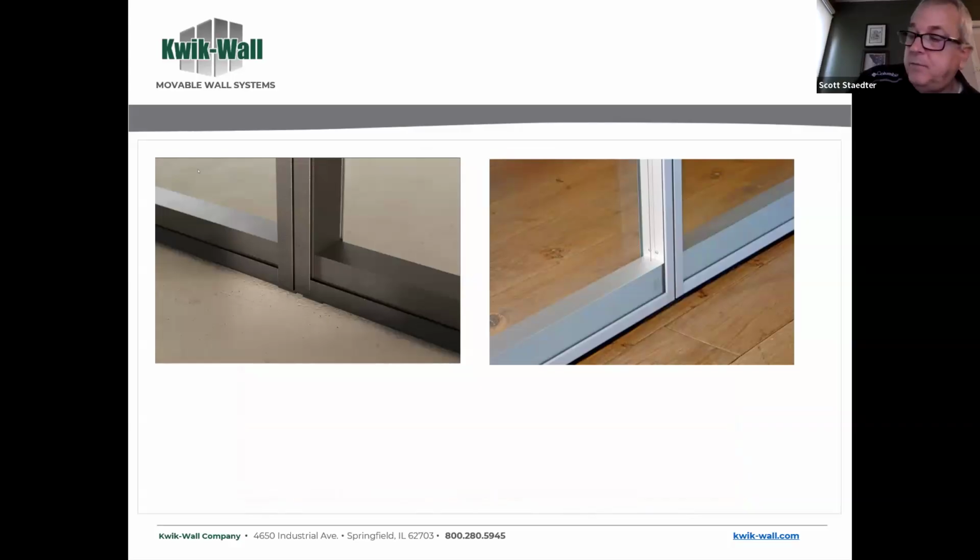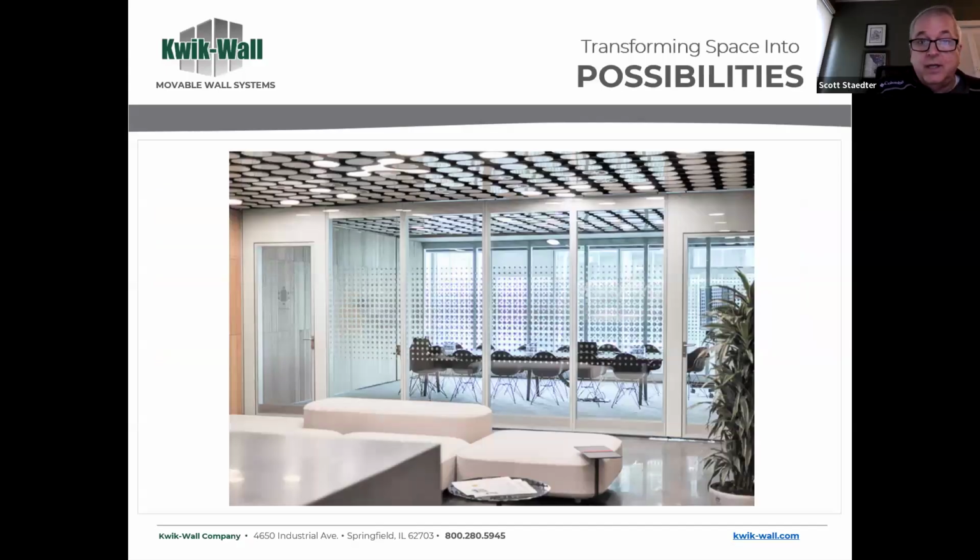The other thing that you might want to consider is these are photos of two different manufacturers right here. But they both have trim and the glass sits inside of that trimmed edge. And this is right. One, you don't get as much fingerprinting when you're moving the glass because you can hold the edge. But two, it protects the glass edge. So when you're in a school, I would prefer this style of panel with a trimmed edge, to be more protective of that edge of the panel. When you're in an office space, go crazy, like I'm going to show you.